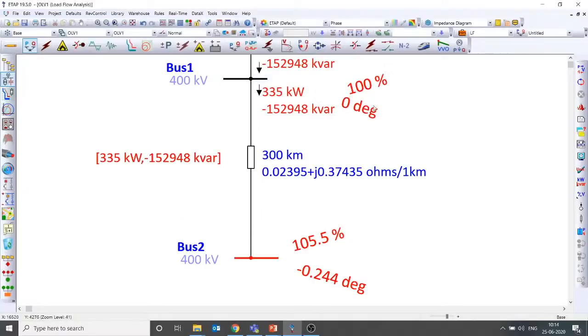That's great. Fine. So what we have modeled now is a 300-kilometer line with no loads connected. The resistance and reactance are identified using transmission line parameters by giving the configuration and line parameters. The loss is 335 kilowatt. We may not really worry about this 335 kilowatt loss unless I tell you another factor. With 335 kilowatt you may be able to electrify at least 3 or 4 small villages, right? The transformer you might see near your home is 100 kVA or 200 kVA. That means you can feed 3 or 4 such transformers with this capacity. Imagine how many homes you can electrify.